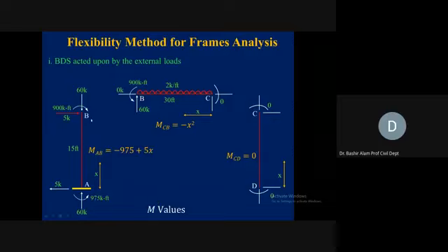We have split them, we have opened the joints now. At joint B, you can see we have sectioned this. At joint C, you can see we have opened the joint. Now, it is the same analysis we did in problem number 1. If you remember, we started from D, we went to C, from C we went to B, from B to A. You can start from the joint A also and go in the clockwise direction. How can we do it? For that, we need to analyze this determinate structure under the actual load.